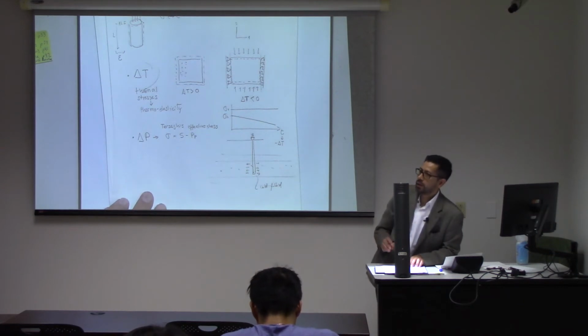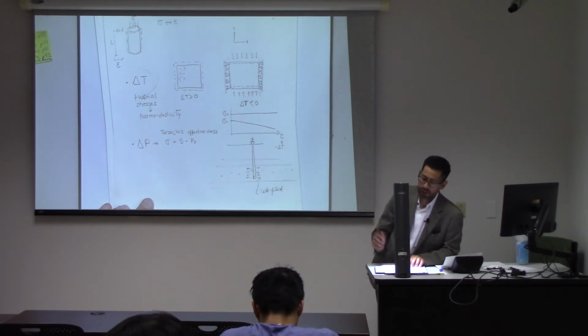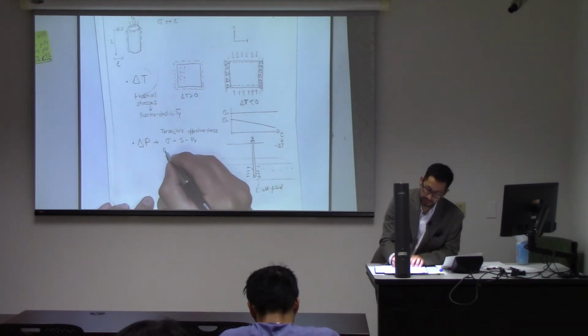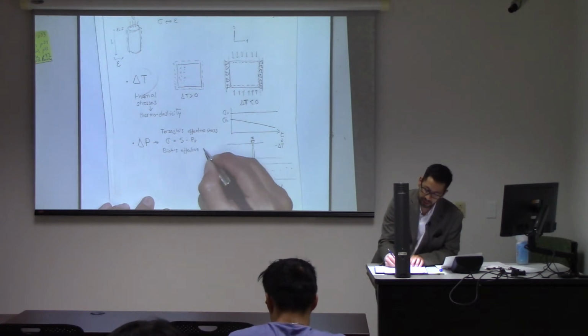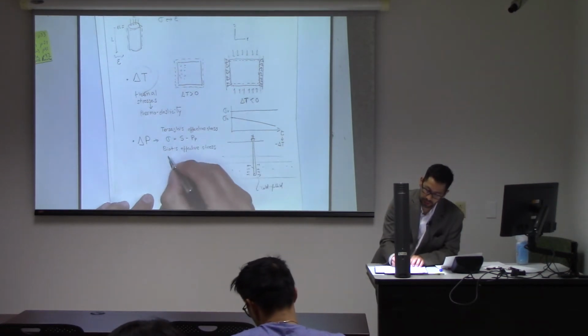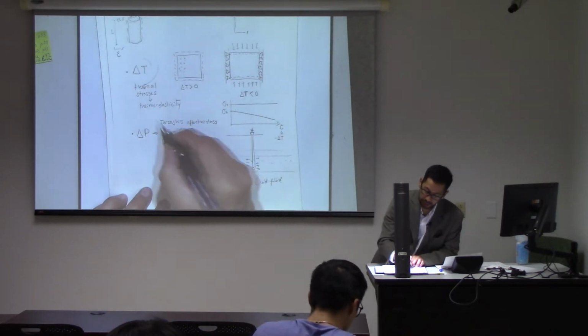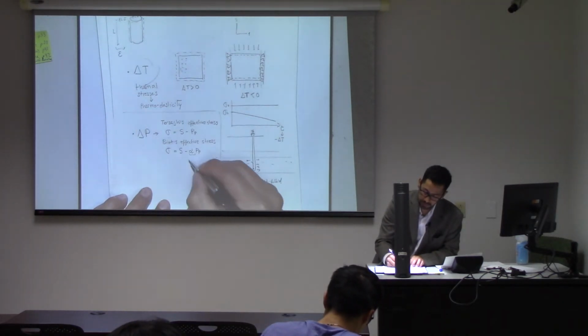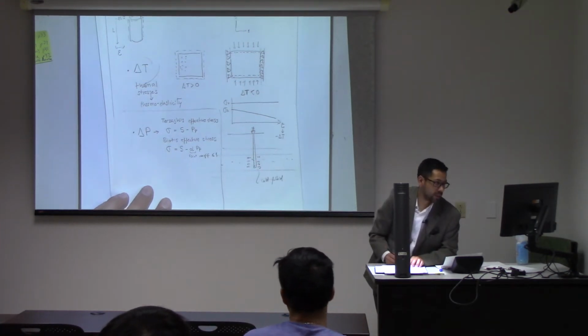But it turns out that when you consider the formation of the rock too, of the solid minerals, this is not very accurate. And instead of that, there is something which is called Biot's effective stress, in which the effective stress is the total stress minus a coefficient, which is called the Biot coefficient, which is equal or less than 1.